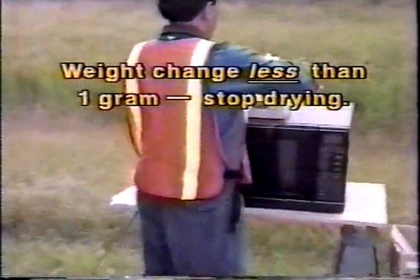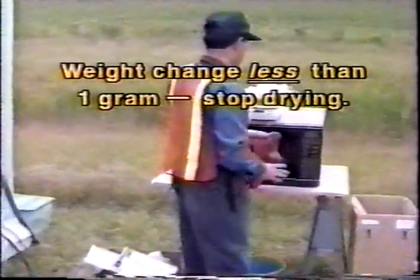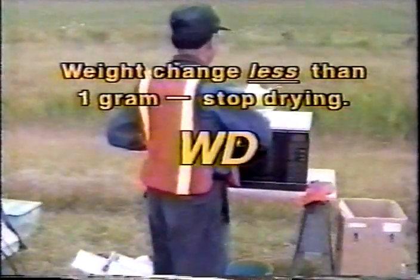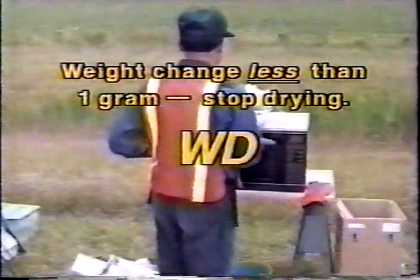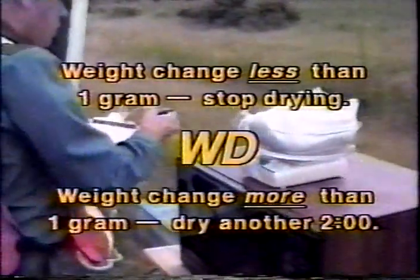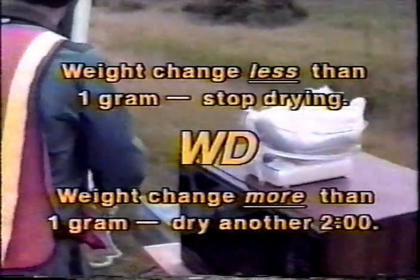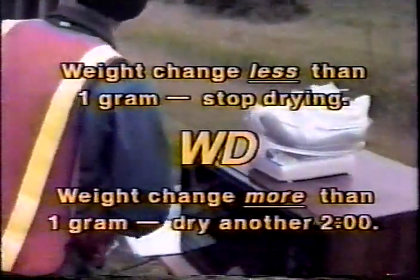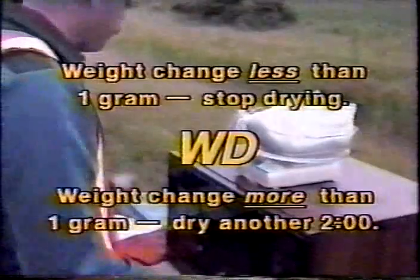Then it's weighed again. If the change in weight is less than 1 gram, the drying should be stopped, and this weight should be recorded as WD, the final dry weight of the sample. But if the weight changes more than 1 gram, the sample should be dried for yet another 2 minutes and reweighed. Then the final weight is recorded as WD.